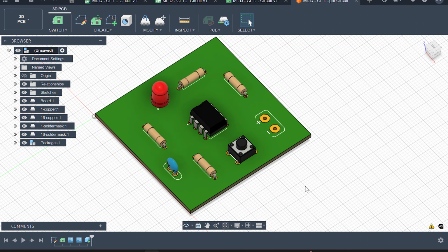If you find all of your connections and all your components are on the same side, it means you made a mistake in the last video here, this step, and you're gonna have to go back to this step and make sure all of our connections, these, are all blue, routed on the bottom. So go back and watch video 2 if you have a mistake. But if we've all been paying attention to the videos and following them correctly, we should have all our paths on the bottom, and we are ready to move on to creating a drawing from our 3D model.